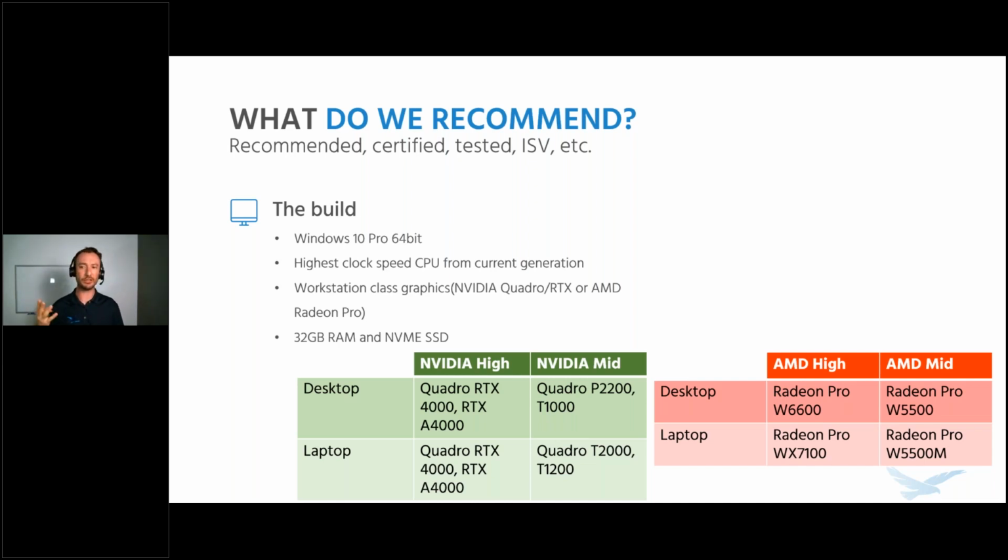The fourth component, I've kind of combined them into one line item there, and that's RAM and storage. Again, I mentioned NVMe storage is king, so it's hard not to get an NVMe storage drive these days. And then RAM. On the SolidWorks certification or minimum requirements page, they list 16 gigabytes of RAM. We are finding that, like on my system, from the screenshot before I showed you, I had one part open and I was already at almost 67% utilization of my RAM.